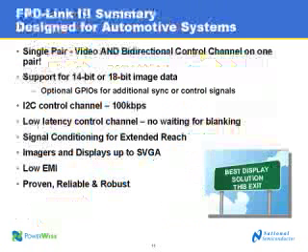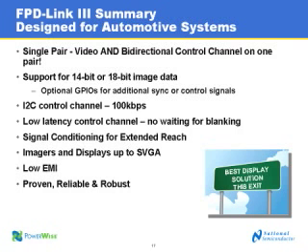Okay. And just to summarize, the FPD-Link III parts really are designed for automotive systems, ground up. The key advantage is this single pair, video and bidirectional control channel on one pair. And these 2 chipset families support both 14-bit or 18-bit image data, really depending on the needs of the application. There's optional GPIOs for additional sync or control signals, and it has an I2C control channel that supports up to 100 kilobits per second, which is the typical I2C control rate for these type of applications.